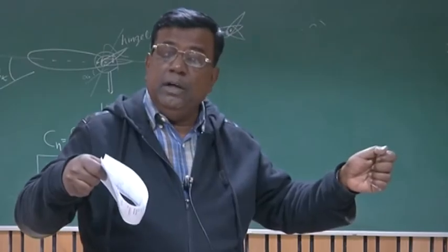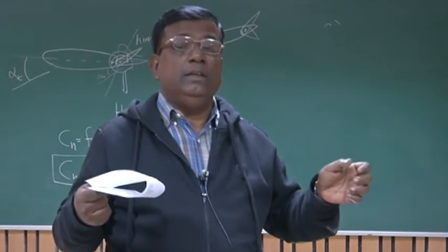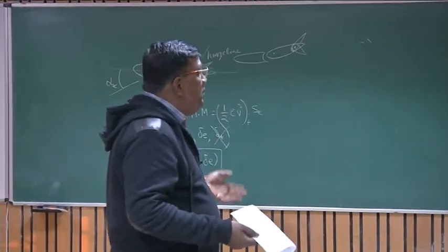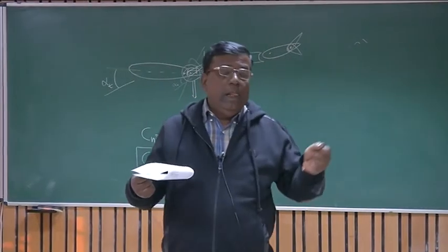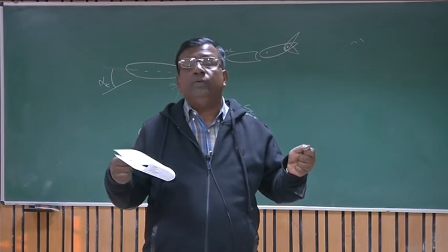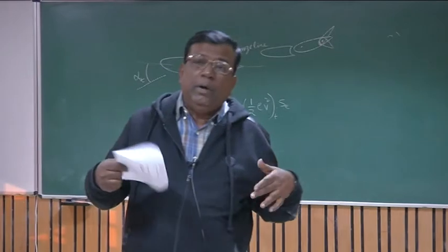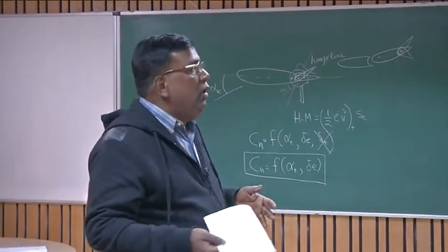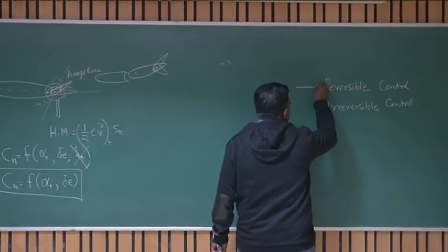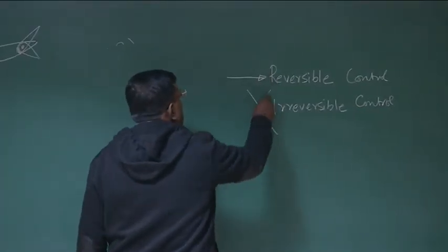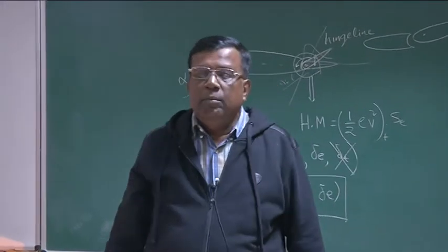But for a reversible control, if I move the elevator, the stick also will move. So they are linked directly like that. However, for an irreversible control, there are boosters, right? So if I move the stick, the elevator will move, but if you move the elevator, the stick will not move, right? So the next part of my lecture, whatever we'll be discussing, is mostly focused on reversible control, not irreversible control. And that is how we will be developing a model.